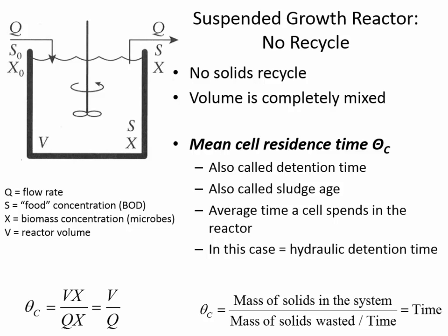And occasionally we'll have mixed liquor volatile suspended solids, MLVSS. And the two are almost identically the same. The volatile suspended solids are the ones that would be burned away if we put it into an oven at a high temperature. And the bacteria fall into that category.